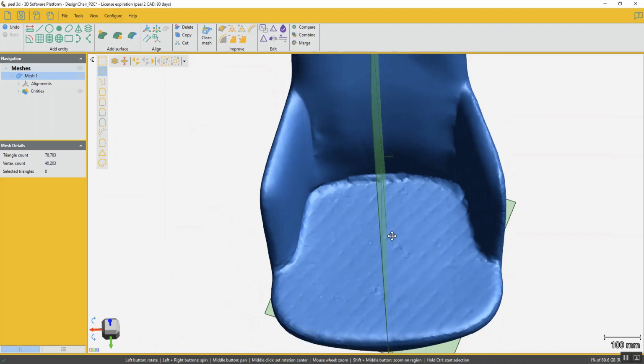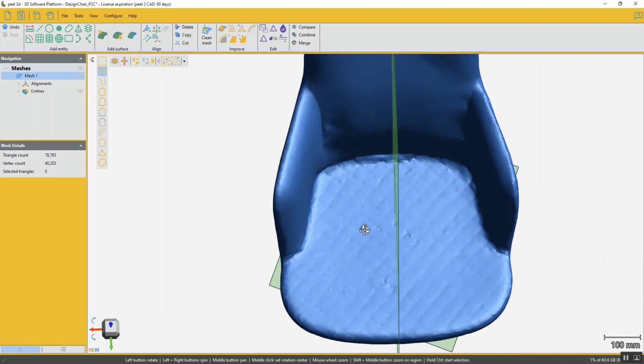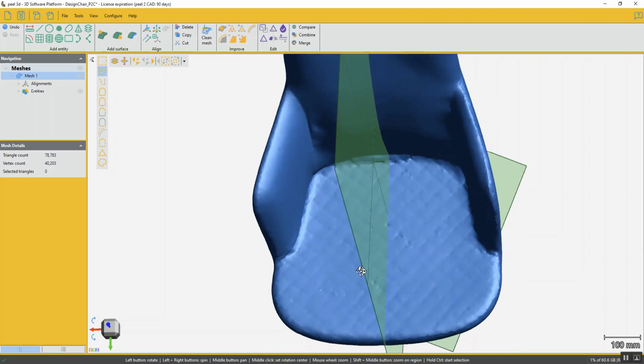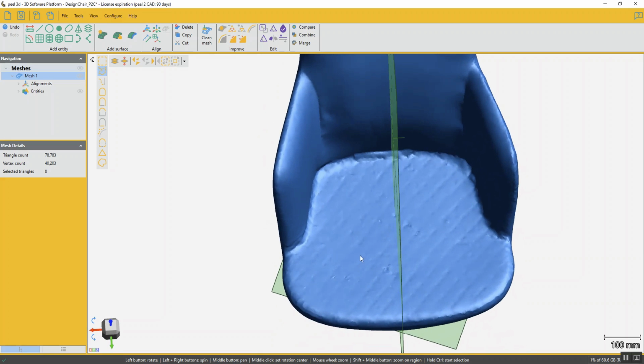Another way to clean things up is by creating holes and then filling them in depending on their form. So in this case, I'm going to use the similar normal tool, and I'll click on this planar area of the bottom seat, and it says unable to create selection with current vertex. In order to allow it to select that region, I'm going to raise my tolerance up, and then it's selecting this region. The reason it wasn't selecting before was because it didn't consider it very planar-like until I said, go a little bit easier on it.